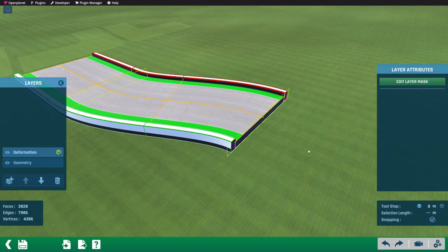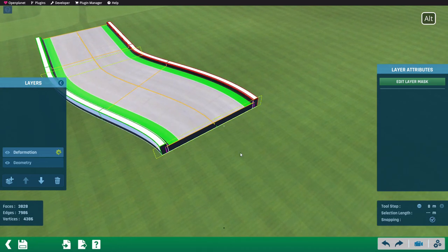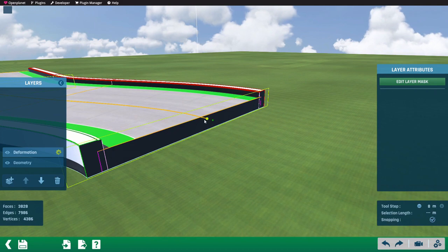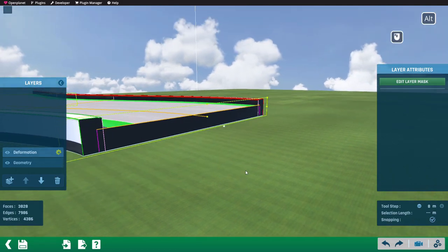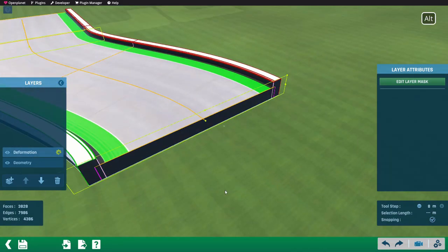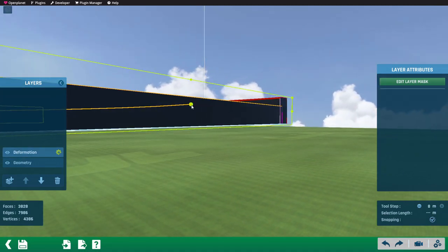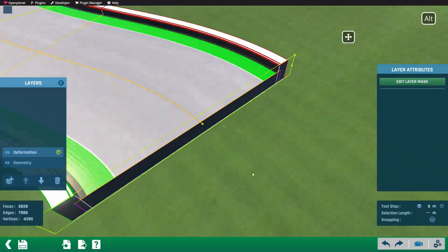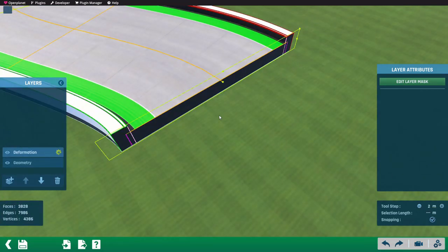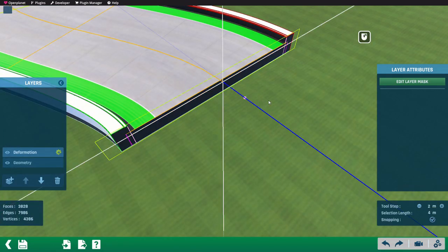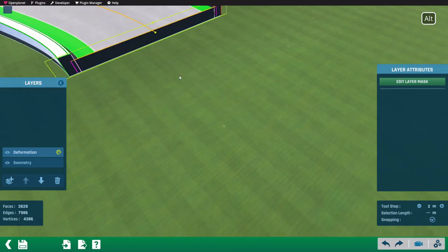Number 3. Editing an existing control frame. Click on the yellow dot at the center of the control frame you wish to edit. This enters the control frame edit mode. Here, you'll notice 4 yellow dots. The central yellow dot allows you to adjust the position of the control frame. Click and hold it with the left mouse button and move it along the 3 axes. Again, you can set intermediate steps by right-clicking.